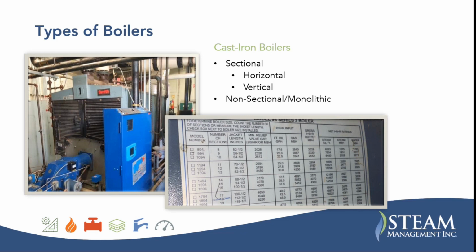I got another comment in here. Boiler efficiency, when drawing the box around the boiler plus condensing economizer, would increase at all load conditions, but the condensing economizer is generally most efficient at max boiler load and max process steam load. Okay. All right. So it's not more efficient at partial loads, Adam is saying.